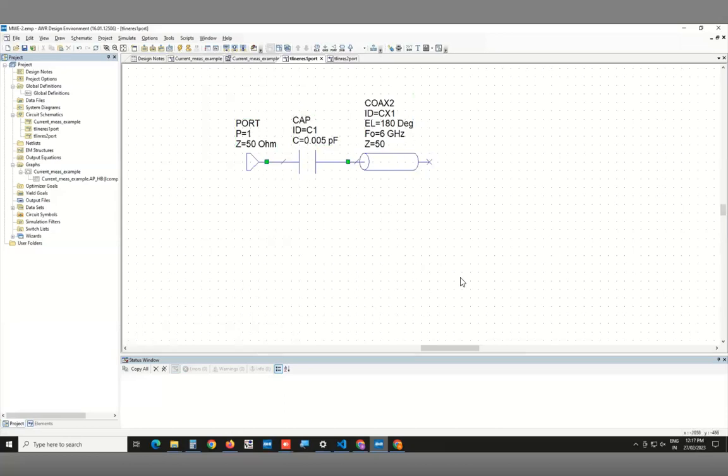So in order to look at the resonance, you have to look at the right quantity, right? And also set up the right frequency range. And again, the hint is there. It's a λ/2 resonator. It's at 6 gigahertz. So the frequency range has to be around 6 gigahertz or so. And you're not going to see anything in magnitude. So let's draw the graph now.